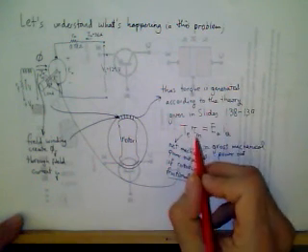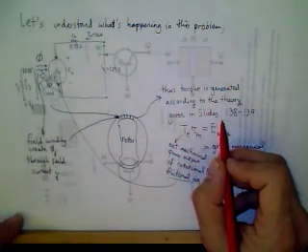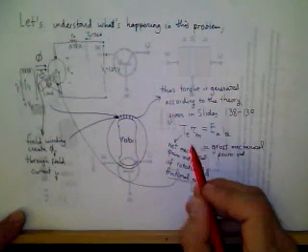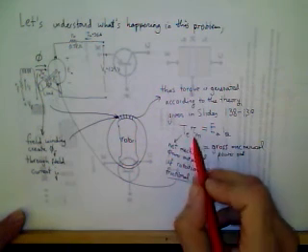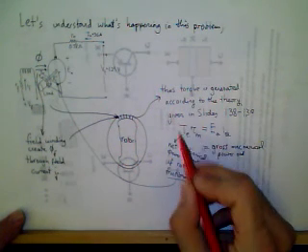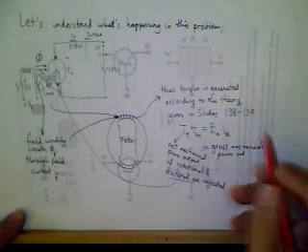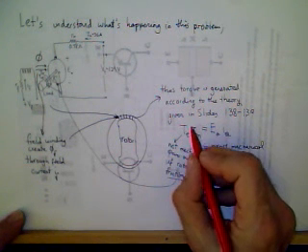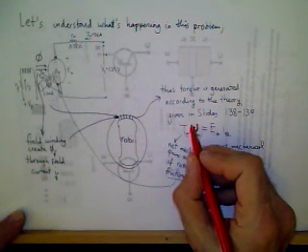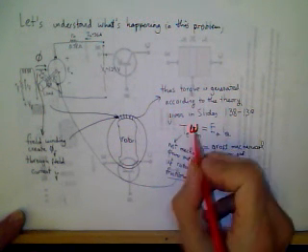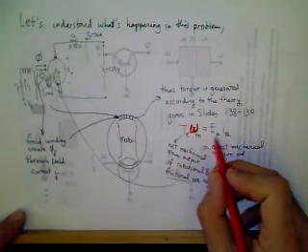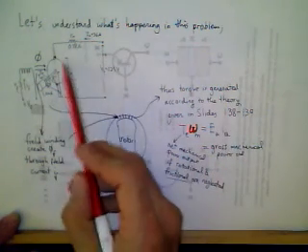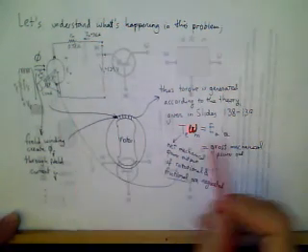This theory states that rotor and stator torques act to create that torque. In the ideal case, the mechanical output power, which is torque times speed, so let's replace this by omega. There's a little mistake here. Torque times speed equals the electrical power input, which is the voltage across the armature and the armature current in the circuit.